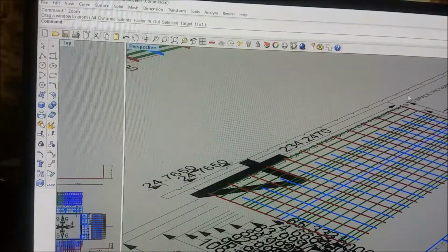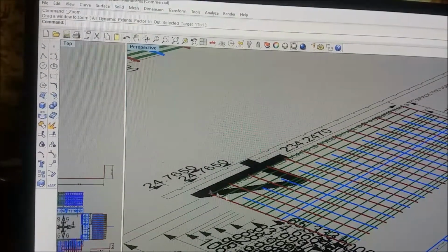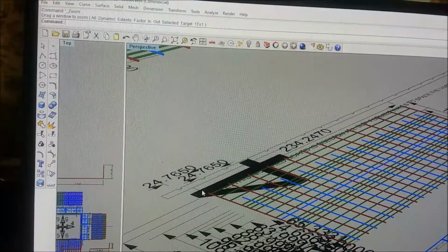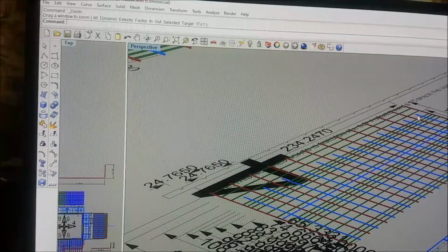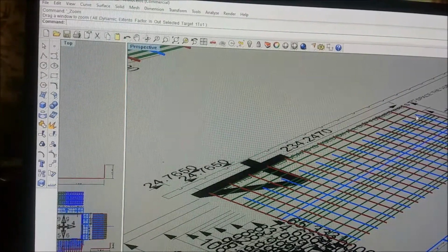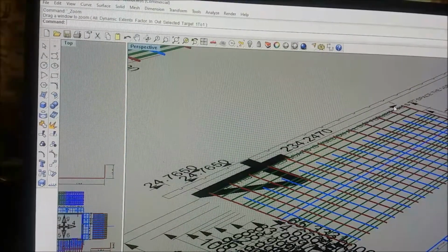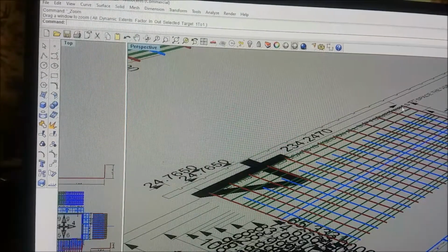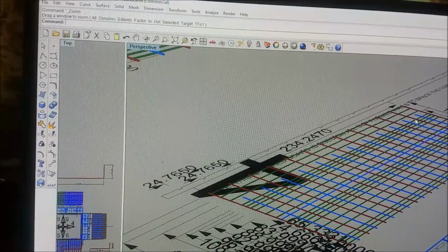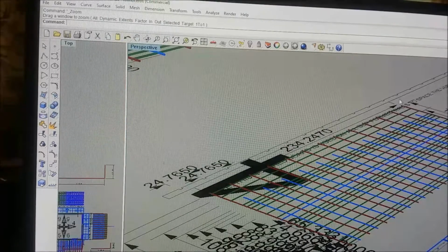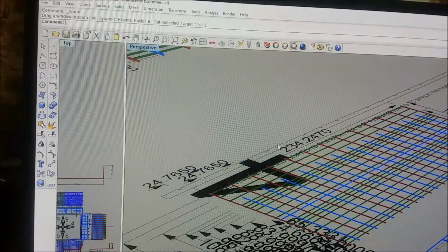Now, this is the length of the wall, and this, I'll draw it on the side you can see, is the height of the wall, right? Now you notice on the length of the wall, we cut the bars, but not in the center. We cut them at 11 foot and 9 foot, because we don't need as many bars of strength up here right at the water line of the tank. This is just airspace in the tank. So we wanted to get more bars closer together. And rather than having to waste half the bars, we cut them off center. And then we put them in a notch board. And so the red, blue, red, blue, red, blue, red, blue, all the way across matches up to these notches.